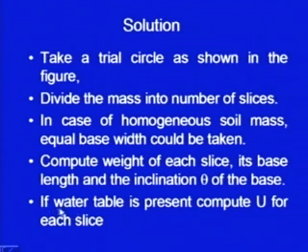And also, if the water table is present, then compute U. Capital U is the force or total pressure. It will be small u into L. Small u you can find out from the flow net, and then you can multiply it with the base length and you can get capital U.